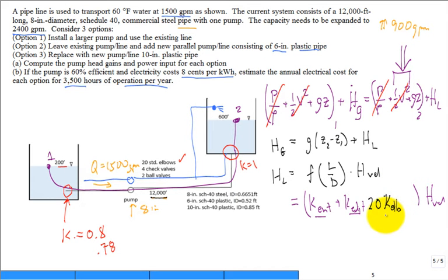How do you get the K of the elbow? A very easy one is table 1:1, and that K of a 90-degree standard elbow is given to be 0.75. If you're staying with the Crane, it's a little more complicated, but they have it. It's basically for the Crane, the standard elbow, they say the K is 30 f_T.